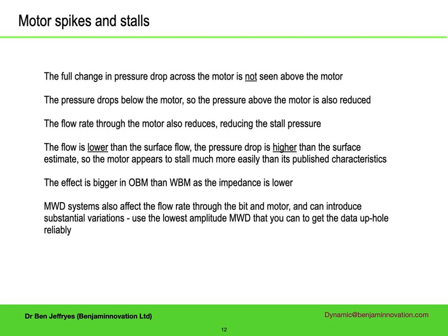The measurement while drilling system can also cause problems with motors. There is a tendency to make the pressure pulses as big as possible when running an MWD system, as this makes the signal easy to detect at surface. However, if you have a huge increase in pressure when the MWD valve shuts, you will also have a very substantial drop in flow through the motor, and this makes it much more likely that the motor will stall.